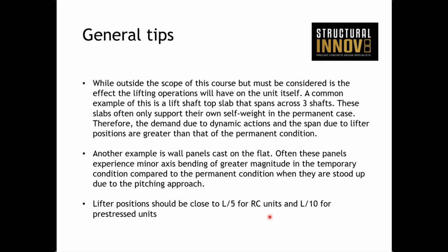And then the last thing is a general rule of thumb that we use: when lifting reinforced concrete units, we use L/5 in from the edge, and for pre-stressed units it's L/10. So L being the span of the unit, over 5 or over 10.